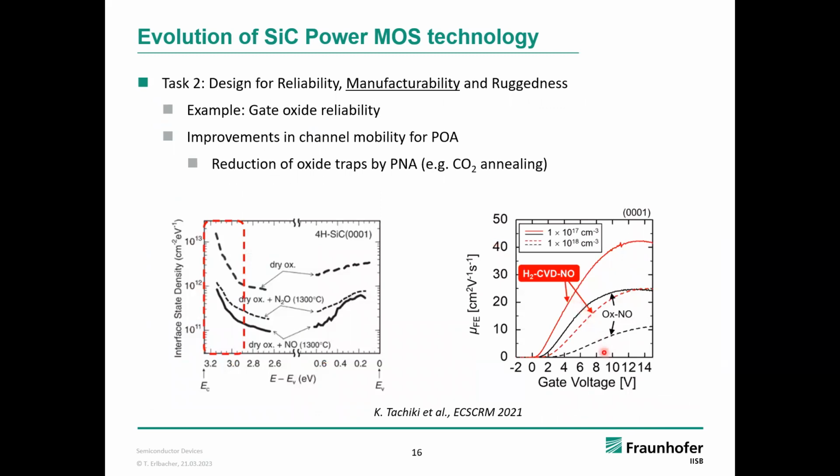There's a long story here with thermal oxidation of silicon carbide, then considering nitrous oxide passivation, like the hydrogen anneal in silicon to passivate interface states, which the nitrogen is doing. Unfortunately, that also gets incorporated into the silicon dioxide. And then the idea is to maybe use a carbon dioxide post-nitridation anneal, and the story goes on and on, mainly because the final or ideal oxidation recipe in silicon carbide has not yet been discovered.